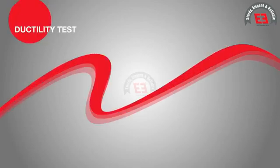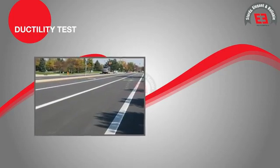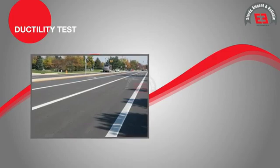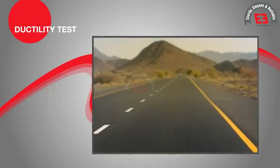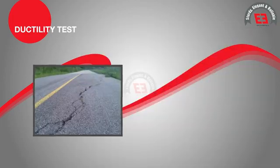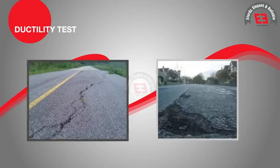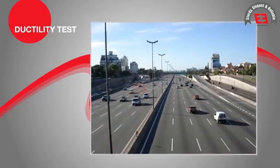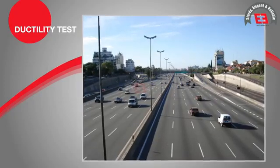Ductility Test. In flexible pavement construction, it is desirable that the bitumen binders used in the bituminous mixes form a ductile thin film around the aggregates. This serves as better physical locking of the aggregates. The binder material, which does not possess sufficient ductility, would crack and spoil the pavement surface. The right ductility value of bitumen binder is an essential requirement for making good highways.